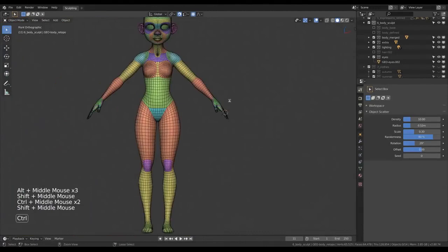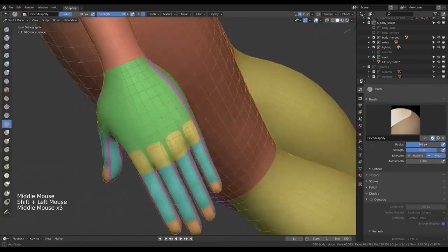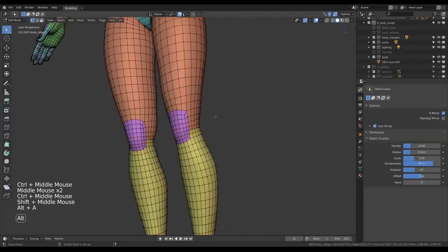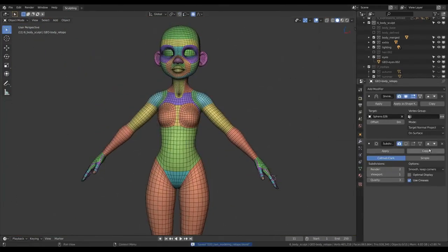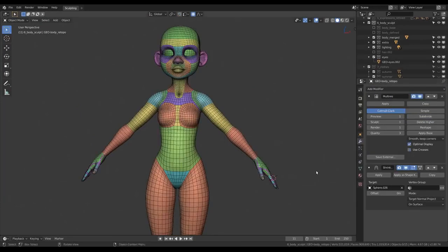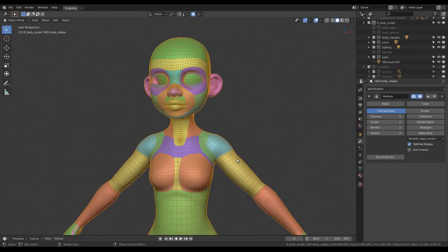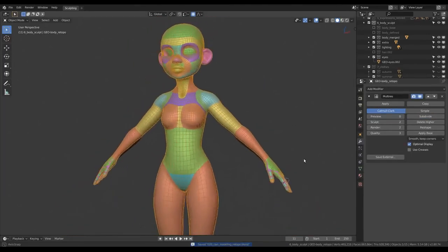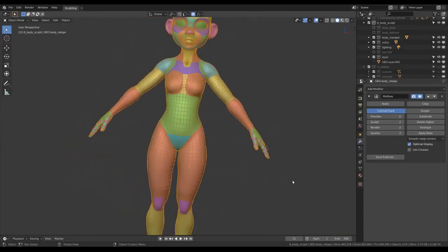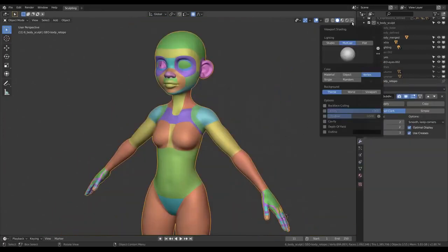At some point, you will have retopologized everything that was sculpted, which is when you will have to model things that weren't already there. But first, add a multi-res modifier, subdivide it a couple of times, and apply the shrinkwrap over it. Then click on Apply Base and get rid of the multi-res modifier too. Now your retopology will have the same volumes as the original sculpt when adding a subdivision surface modifier.